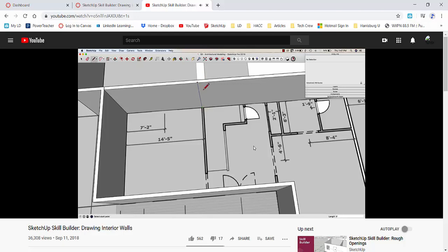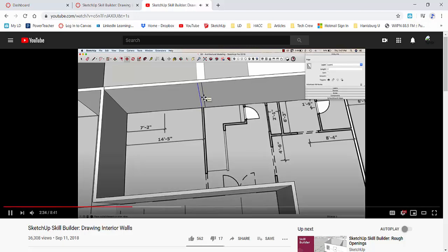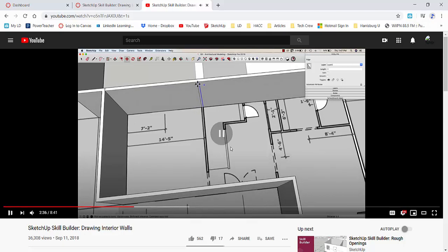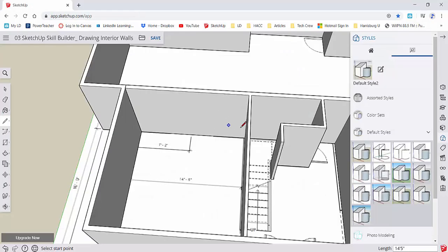So I'm going to snap on the blue axes. Then I'll select that line, scoot it over. What's the wall width? This looks like an interior wall. I'm going to say this is 3.5, so I'm going to type 3.5. Remember, you hit Control to make a copy. So he had the line tool. You could also just use the rectangle tool.